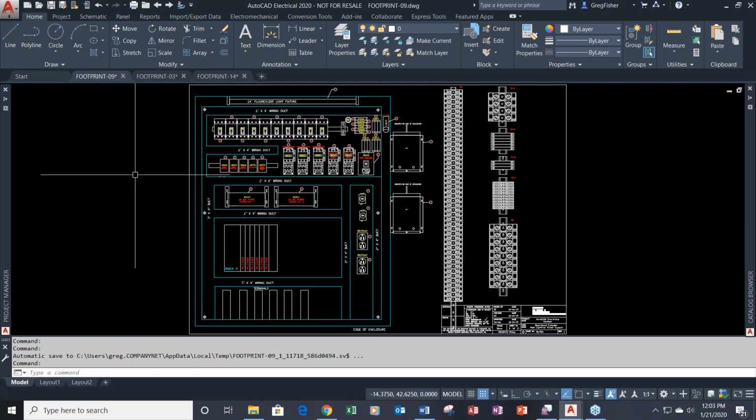Ideally, in a perfect world, we start the process at the schematic level. That way, when you go to design the panel, as you're going to see here shortly, I'm going to pull up a list of all the components that need to go in my panel. So it's a nice check system. Whatever I have in the schematics, I need to put in the panel. But not everybody lives in the perfect or ideal world. I have many customers that have to start with the design of the panel first before they have one schematic even drawn.